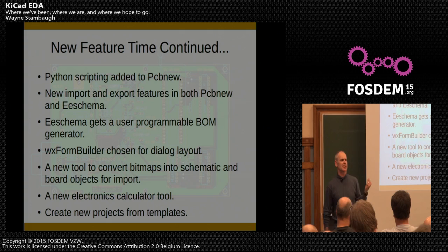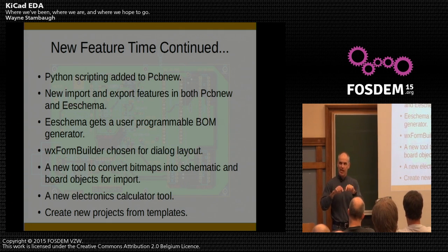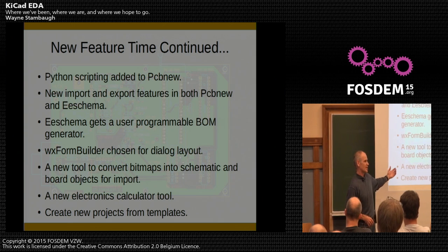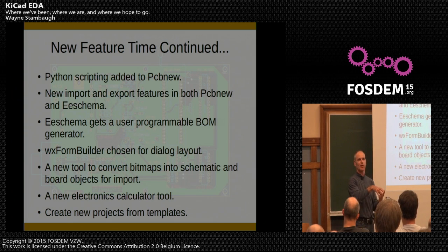There are quite a few templates, like some of the standard form factor boards, like the Stellaris standard form boards. There's a board layout with all the I/O in the correct place, and you want to do a project with that board. Say you want to make a daughter card to mount to it. You just suck that in. Everything's in the right place. The holes are in the right place, and then you can lay your schematic out around all the existing stuff.